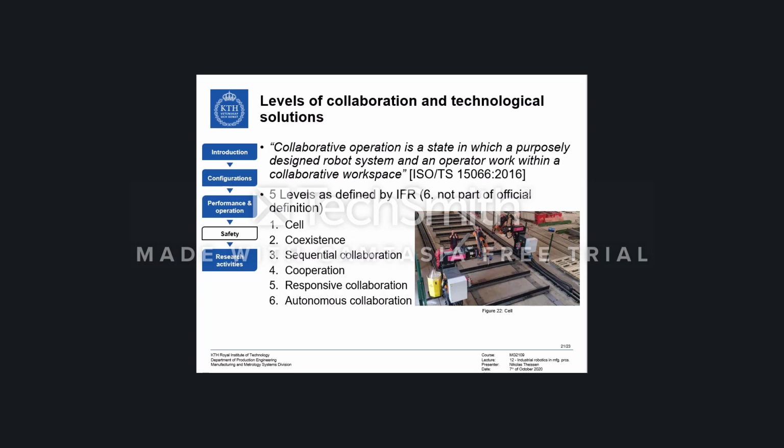So, characteristic for a cell are fences. Fences are used to prevent entry to the robot's working space. The fence is also a preventive action against losing parts out of the gripper. Barriers could be a different type of protection, preventing the worker from entering the cell through the load or unload area. In special cases like laser cutting, arc welding and water jet applications, the system is completely encapsulated.